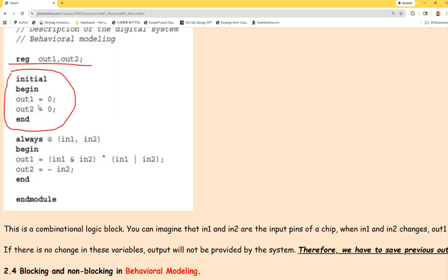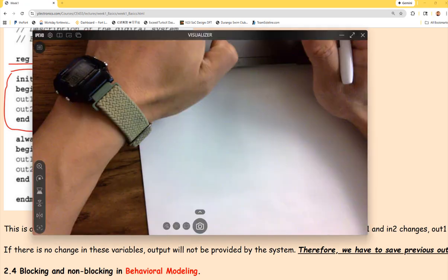Which means if you use it in Cadence, right? In Cadence you are programming. Remember in the VLSI, you didn't take it, but other people took Cadence, all the tutorials. Remember at the very beginning the counter design for Genus, right? The counter design for one of the tutorials is actually Verilog code, and you synthesize that in Genus, and then in Innovus, you load all the netlist files and all the technology files into Innovus, and then convert everything to a layout. But the very first step was a netlist. Let me just draw it here, just in case. It's easy to get confused actually.